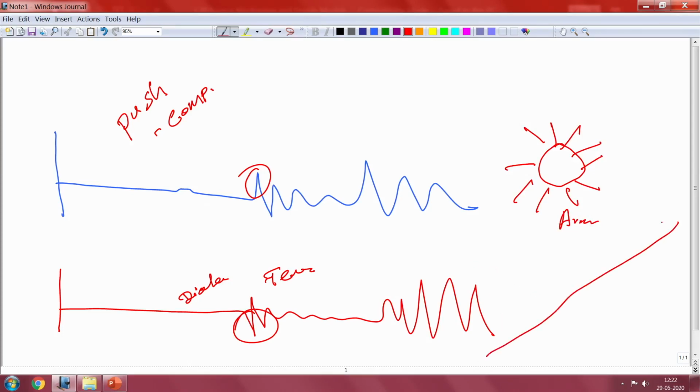In a natural earthquake it may not be like that, since it happens with rupturing. For example, this is the fault. You will get rupture larger at one place and higher at another place, so depending upon where the seismic instrument is located, you will get tension or compression. Describing this tension-compression combination of what happens at the source is called the source mechanism.